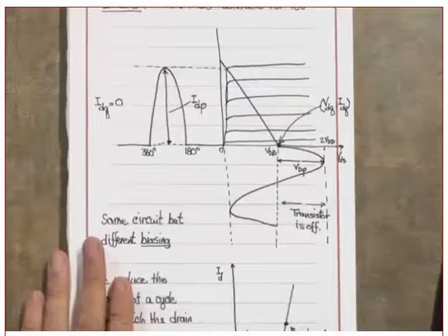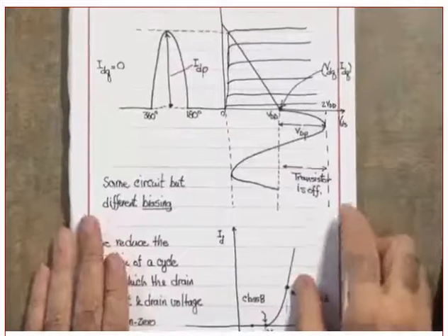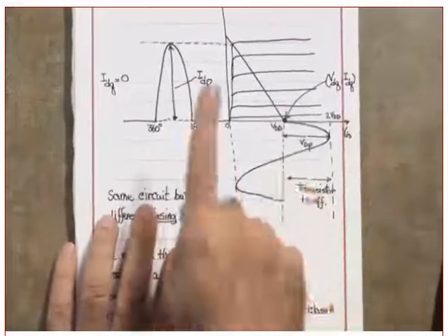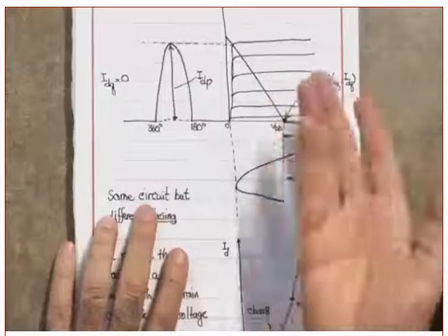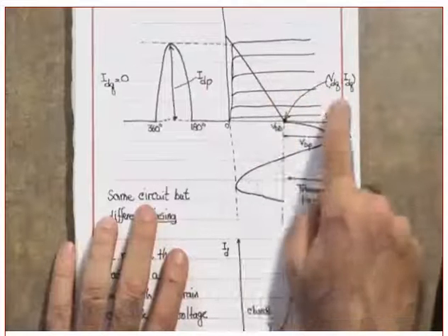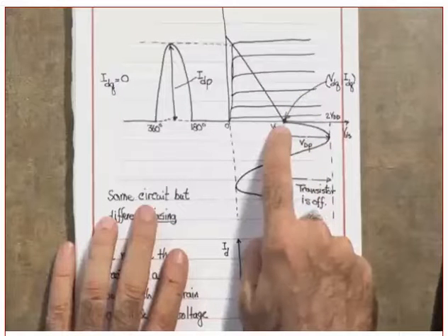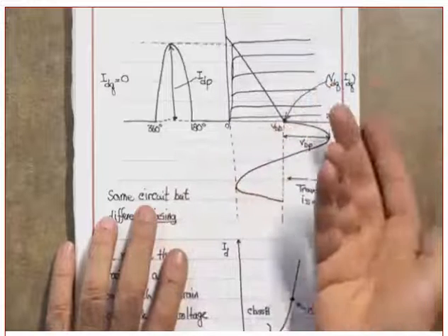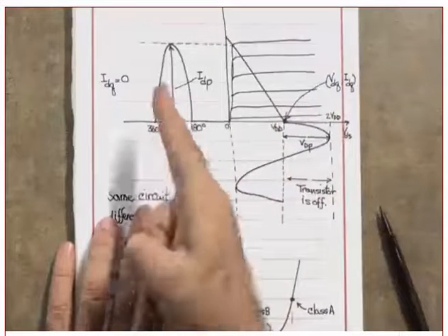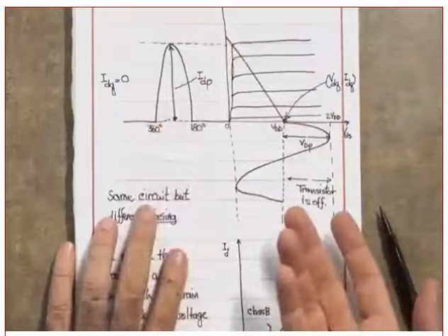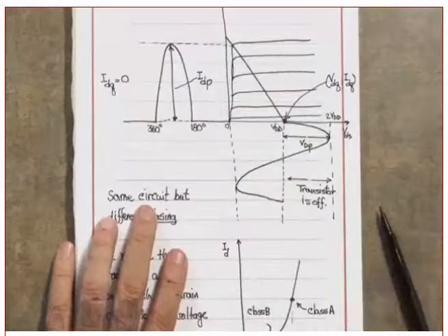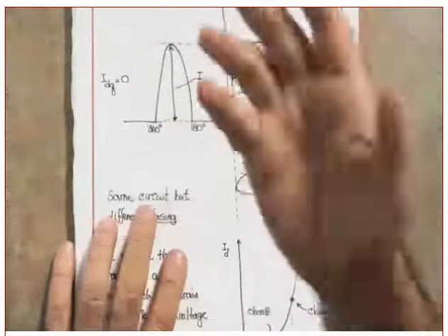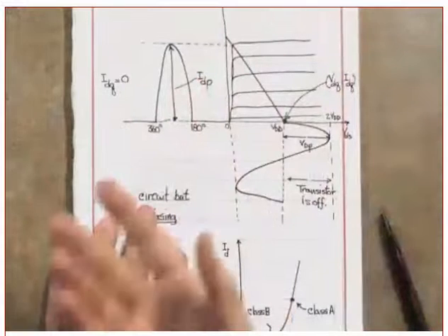You're lost in translation, because you don't have a background in electronics. That's the problem. Okay, concentrate. Where is the quiescent point here? The operating point. Where is it? This point. What is the coordinate of this? It's VDD, comma 0, comma 0. The current here is 0. But does it have DC? It has DC. How do I get the DC component? Through finding the Fourier series coefficient at omega equal to 0, like we did earlier in the semester and in 301.